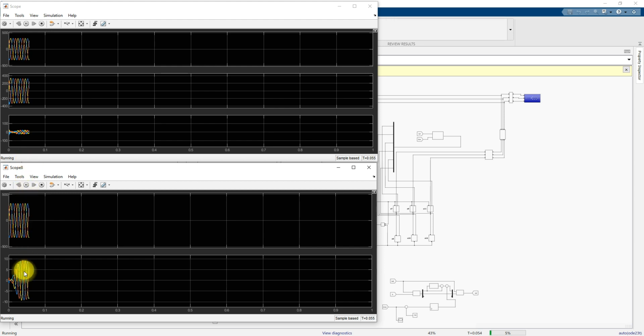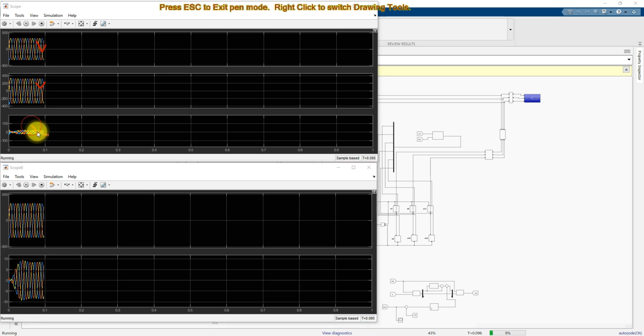So here you can see that the source current is sinusoidal only, and then you can see the grid voltage, the load voltage, and the injection voltage by means of UPQC in the line. So this is the source voltage and source current, and you can see that the system is under normal condition, operated with the nonlinear load. The source current nature is sinusoidal, so no problem.